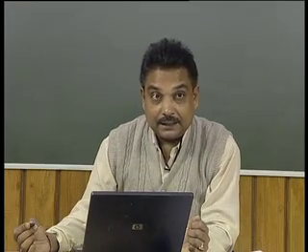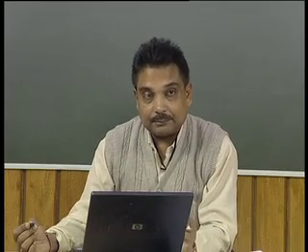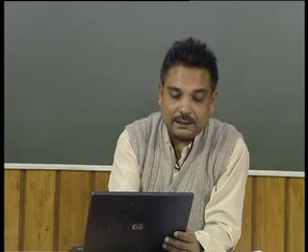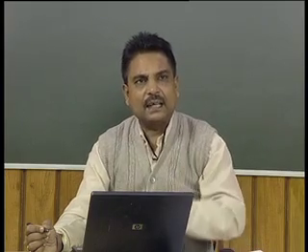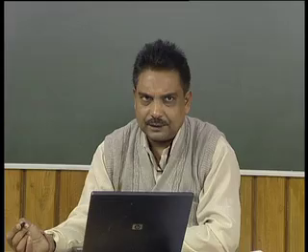Initially it is at Ti, and then the surface is maintained at a constant temperature Ts, which is a lower temperature than Ti. That means Ts is lower than Ti. So, heat transfer will take place from the solid wall to the environment because of the driving force for heat transfer. And this is a conduction phenomenon. We are not considering the convection here because the surface temperature has been assumed to be a constant temperature case.